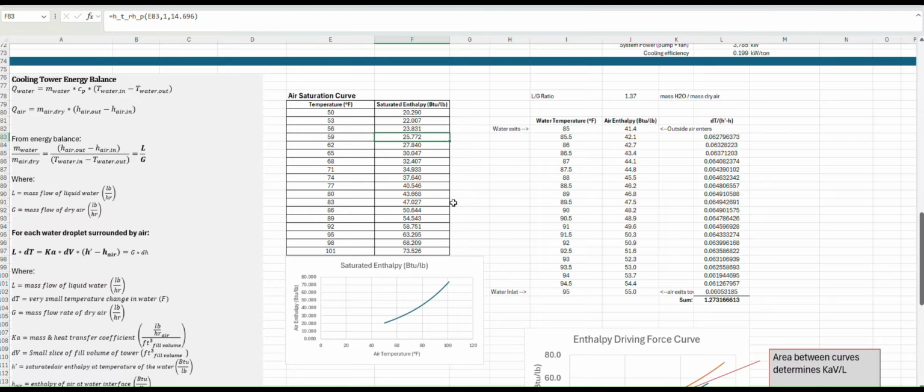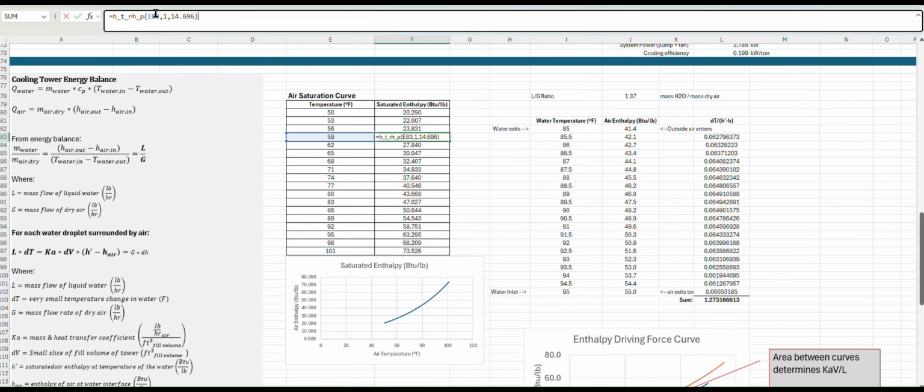You can look these values up in a psychrometric chart, and it's the same thing as the way I'm calculating it in the background. So it's saying, what is my enthalpy if I know temperature and relative humidity and atmospheric pressure? And the temperature input is my arbitrary temperature that I just want to know what my saturated enthalpy would be.